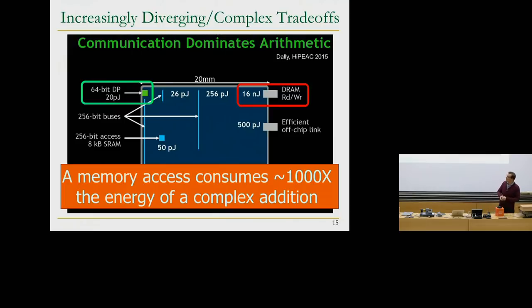And as a result, people have been following that theory, and transistors have been becoming more efficient for the last 70 years. Whereas memory access, which is not fully transistor-based, as we will see later on in DRAM, as you have seen a little bit actually, it's really based on the interconnect, the wires. That has not scaled as much. As a result, you have this huge disparity right now. Memory access is much more costly than even a complex arithmetic operation.